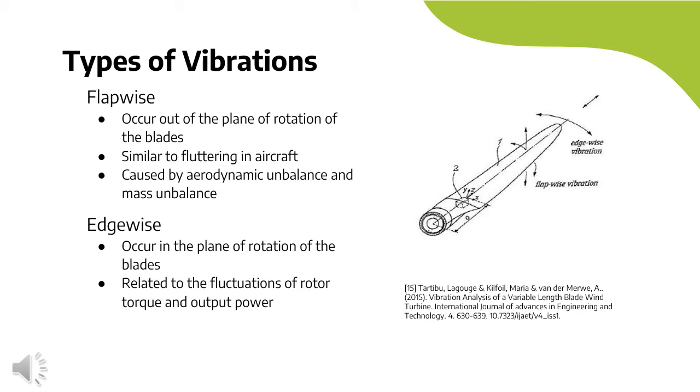Because most wind turbines are extremely tall and are placed in areas of turbulent, high wind speed, high vibration occurs at the top of towers and in the blades. Horizontal axis wind turbines in particular also experience extreme problems with vibrations due to the heavy loads on top of the tower, which includes a generator, gearbox, and other installation kits. Wind excitation, earthquake excitation, and waves for offshore turbines are major sources of structural vibrations.